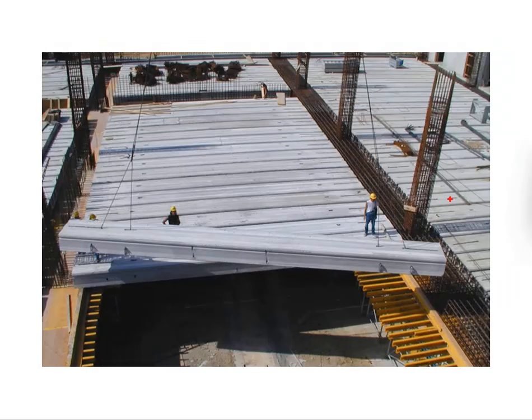Besides that, even if you have slabs from both sides, torsion can also happen within the beam. This is something interesting about precast concrete structure design. For a typical reinforced concrete design, we only design for one stage. That means at the service stage. We analyze the load based on the functions of the building when the building is put into service.